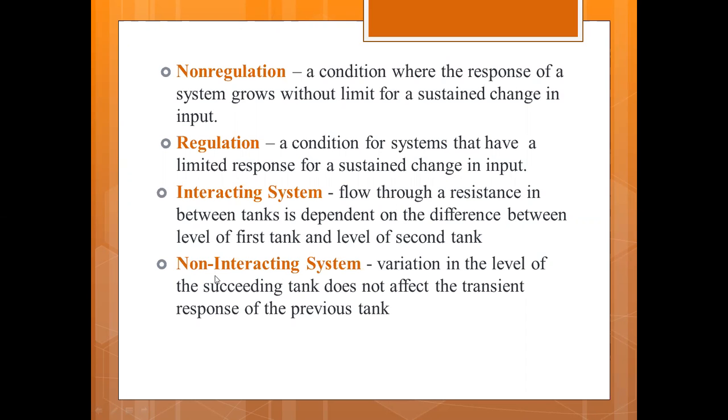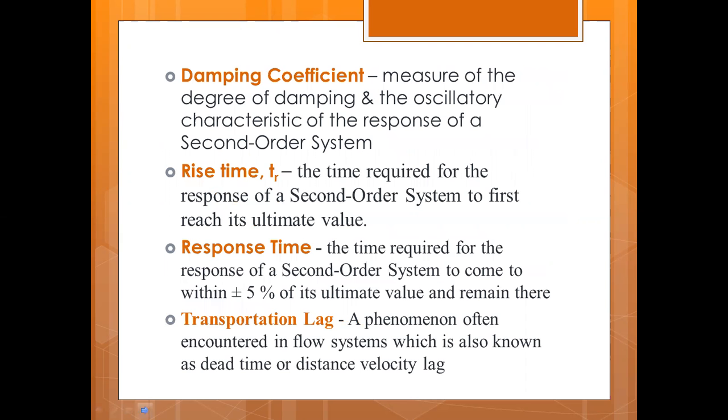Okay? Non-interaction is simpler because the variation in the level of the succeeding tank does not affect whatsoever the transient response of the previous tank. The damping coefficient is the measure of the degree of damping in the oscillatory characteristic of the response of a second order system.